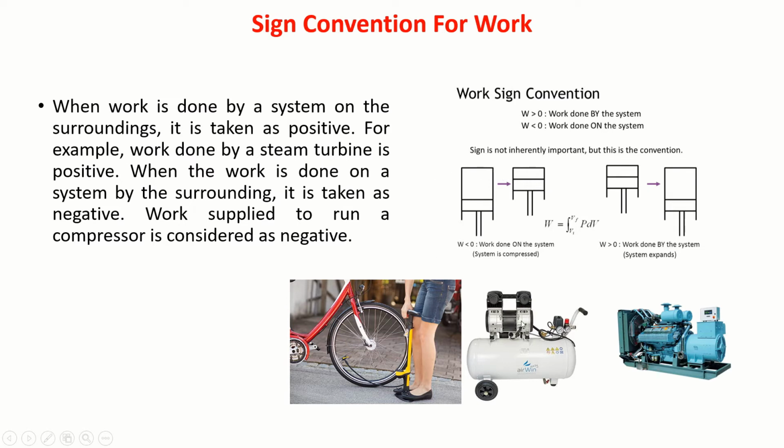So here you consider a compressor is there. It is sucking air, compressing it to a higher pressure. So work done, we can calculate P dV, right? V1 to Vf. I'll tell you later what exactly this is. Work is done on this. This is a negative work. Work is done by the surroundings on the system. If you consider this as the system, and by supplying the work, I've decreased its volume from here to here, but pressure has increased. That's what exactly a compressor does.